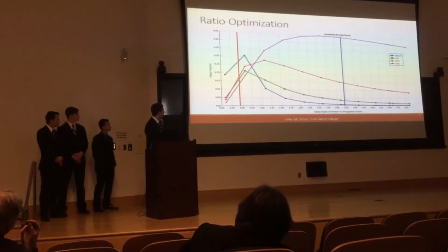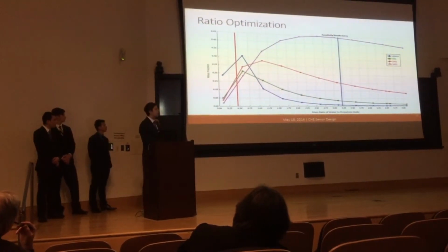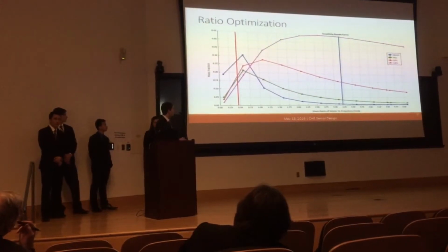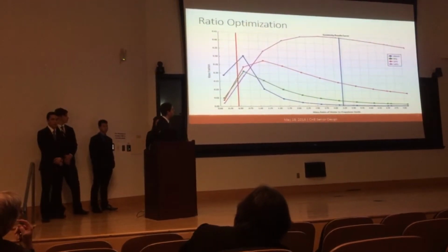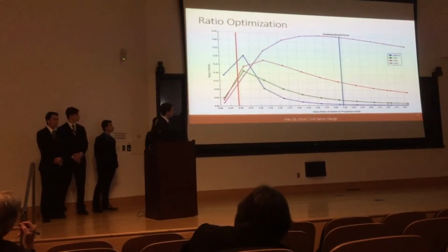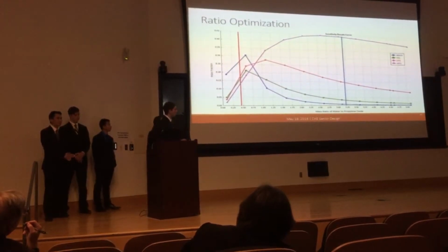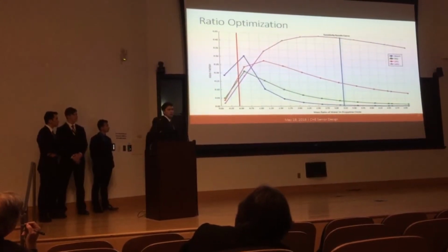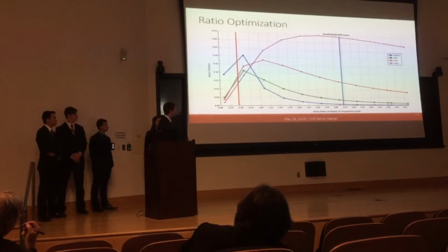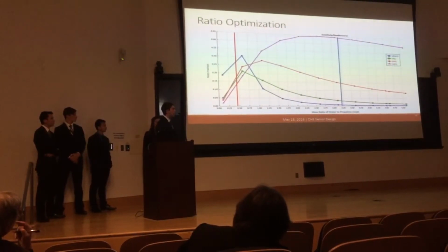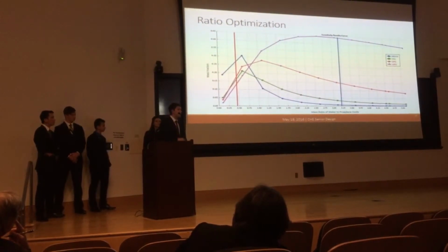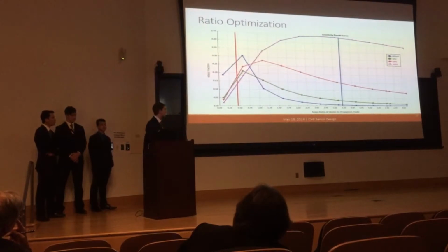However, by running the sensitivity analysis in Aspen, we were able to figure out the maximum production is somewhere around 2.3 to 2.4. We decided that we would sacrifice a small amount of monopropylene glycol to continue to reduce the heavy production and optimize the process, due to the high cost of separating the heavier tetramer.